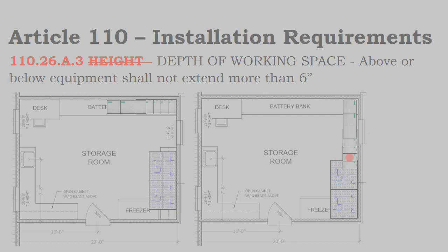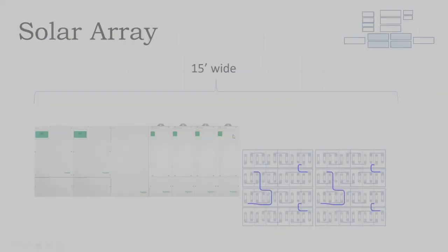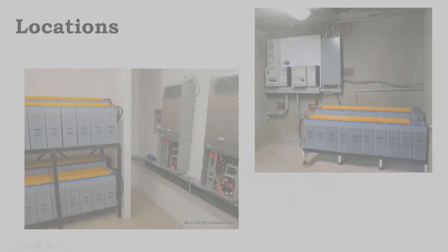charge controllers, there's not much going on in those charge controllers. There's 4 of them. There's no disconnects. It's just 2 wire terminals each. There's not much going to fail with the charge controllers. The client's never going to need to access those charge controllers. And so I'm just going to put them above the batteries rather than to the side. That would be a code violation as well.